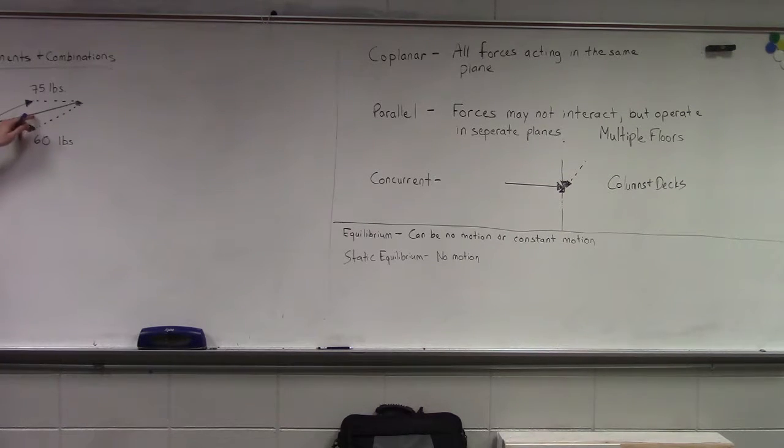So once we have our resultant, now we know I don't need those two connections. I can simply install one connection, equal in magnitude to our resultant, but in the opposite direction. So the first part of your homework will be, and we'll work through an example here, determining some resultants. They give you some examples in the class, or in the book.